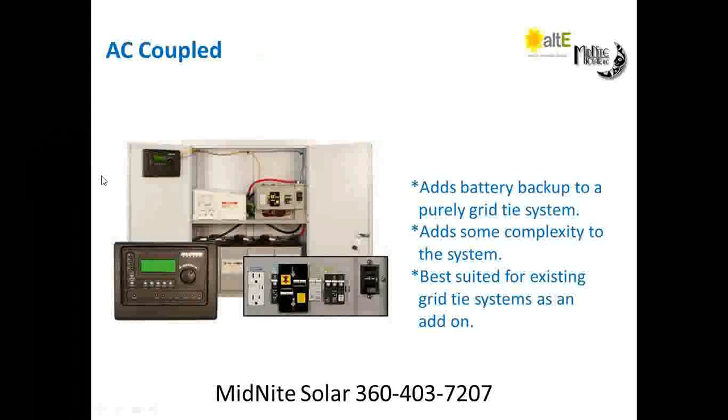I need to mention that it will usually be more cost-effective to choose the grid type battery backup when you know that they want battery backup only than to buy 2 inverters. Basically what Kim is saying is that from a financial standpoint, you're going to be ahead of the game to do a DC coupled or a battery-based grid tie system from the start than to do, say, a Fronius grid tie inverter now and add this system to it a year from now. Just because you're buying 2 inverters, whereas if you do the battery-based grid tie, you're buying a single inverter and a charge controller. So it's going to be a little less money and obviously less installer time on site because it's 1 install instead of 2.